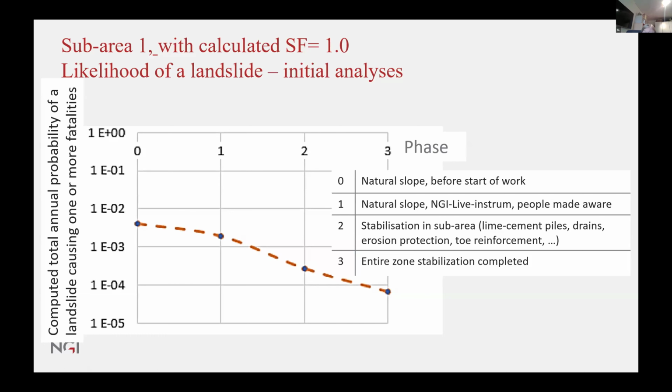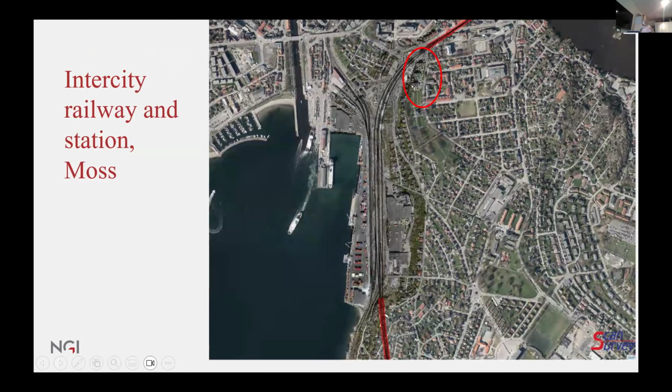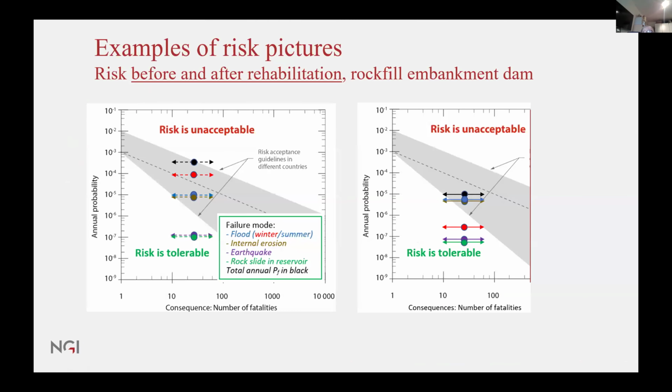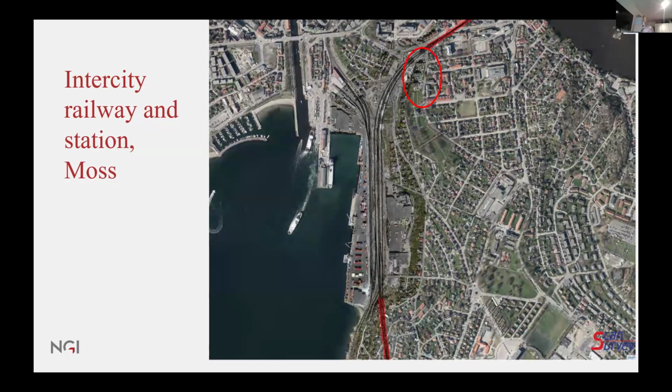But what happened, and it just happened in the last 6 months, so this is the area where we had the weakest slopes. And so we were stabilizing here, putting in some piles, and then the displacements downwards were moving further and further towards the port. So we did some finite element analysis and looked at what displacement could be allowed before there would be a landslide occurring.